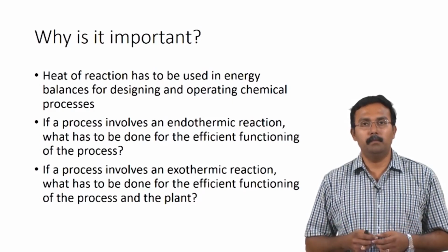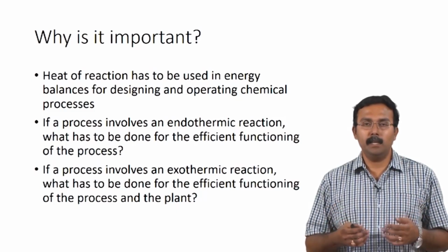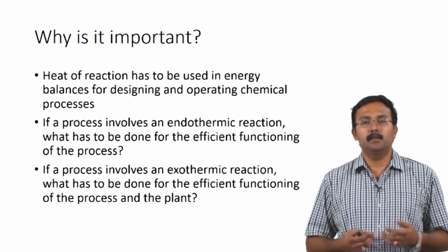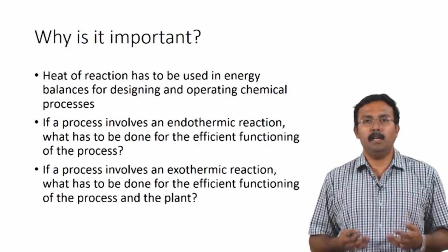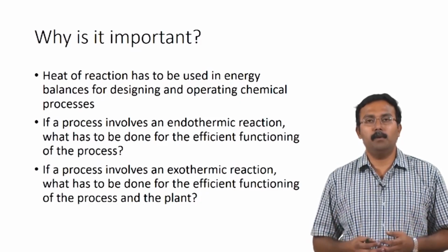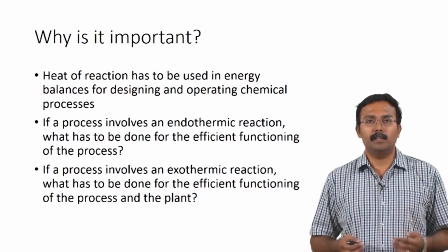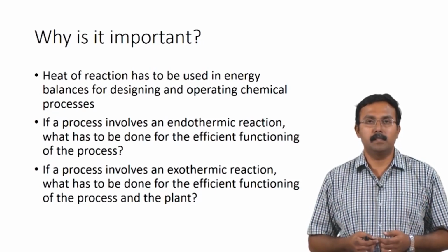So, that is a problem. In an endothermic reaction, the temperature will keep dropping further and further, so that the rate of the reaction will keep decreasing. This would mean you will not be able to produce the desired product. So, that would be a serious problem in an industry too. So, for these reasons you want to maintain the temperature at certain desirable limits.